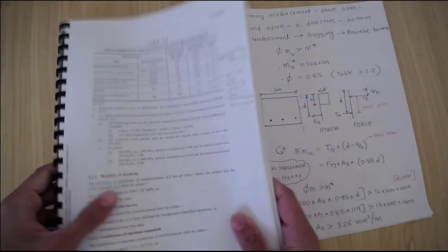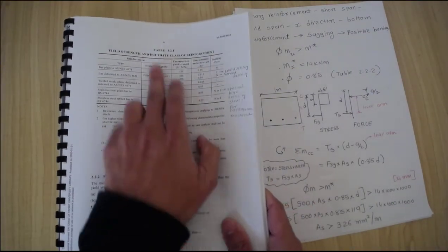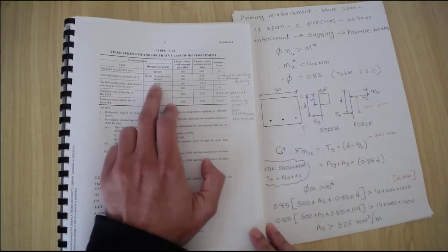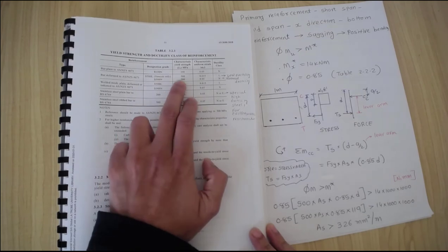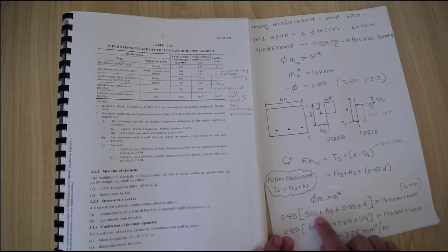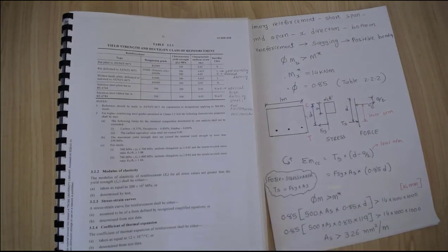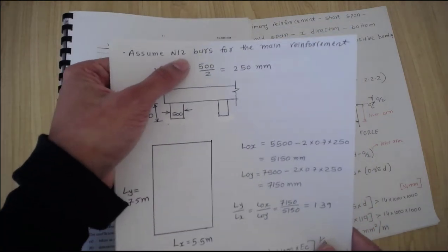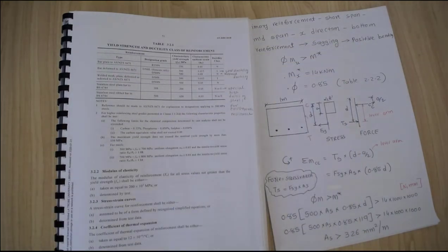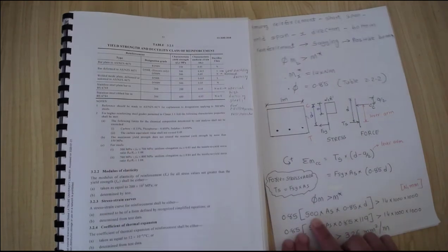There you go. At the start of the standards, on page number 51, you can find this N bar. Somewhere under ductility, N bar, we have 500 megapascals. That's given here. So therefore we take it as 500 megapascals, and at the start we assumed class N. Let me find that. At the start we assumed N12 class bars. Generally we use N12 and N16 bars in the slabs. So for that N we have 500 megapascals.